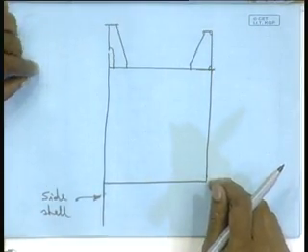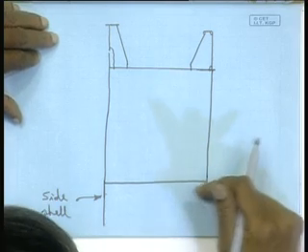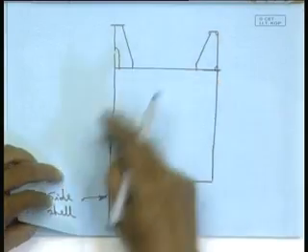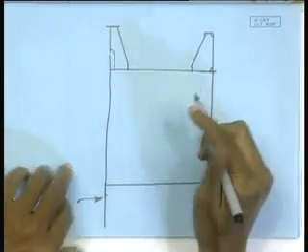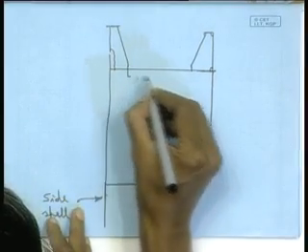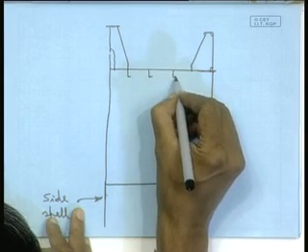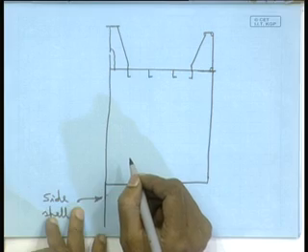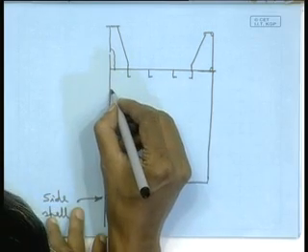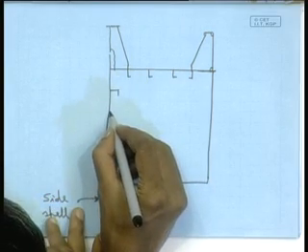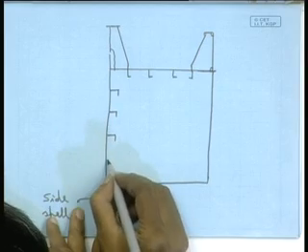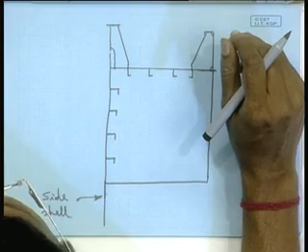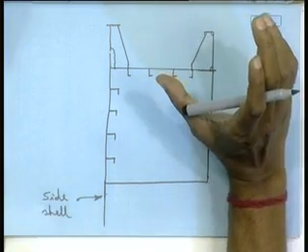Bringing that same plate, vertical plate or a girder, and in addition I am having a fully horizontal plate, thereby completing a box like thing, and this is now stiffened. These are my so called deck longitudinals, right. This part of the side shell is also longitudinally stiffened, again for the simple reason that a longitudinally stiffened system gives me best buckling strength.